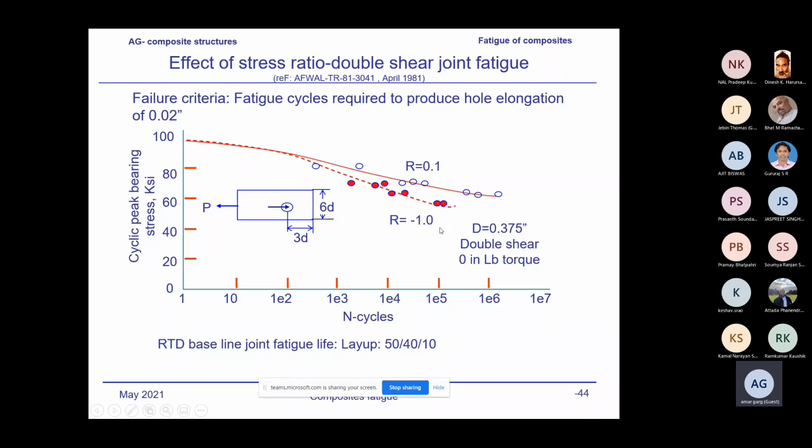Normally, when we are trying to determine reliability, we work conservatively and determine the endurance limit for R equal to -1 in general, unless one is sure that you would never have any cycle near R equal to -1, and design with whatever the actual value is. But normally, the practice would be to consider R equal to -1 conservatively when we are considering the endurance limit values.